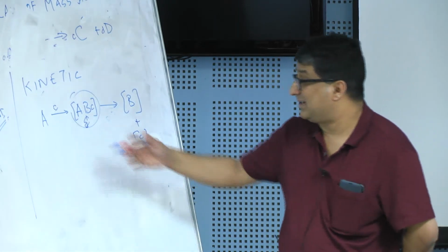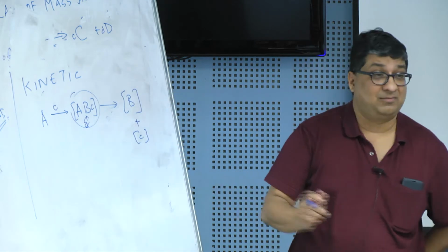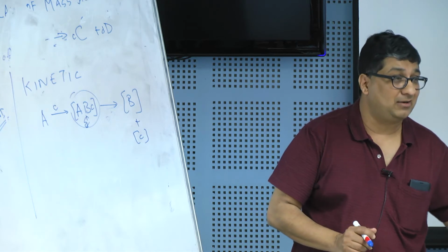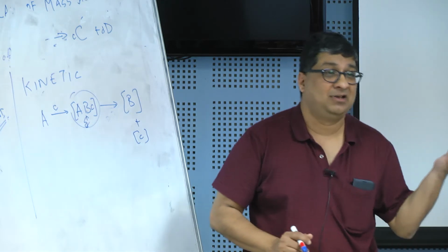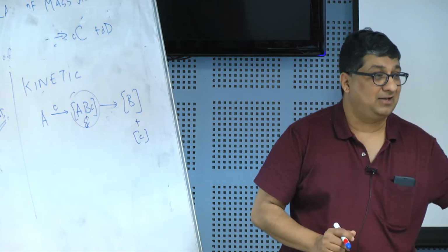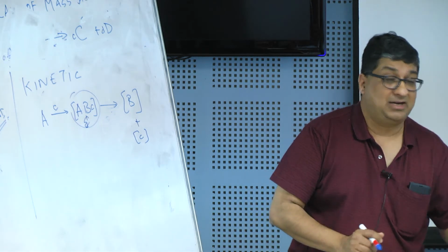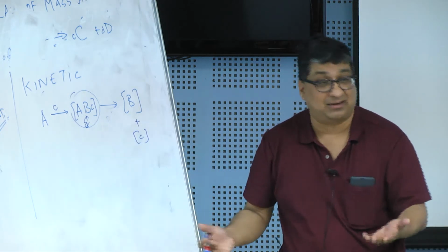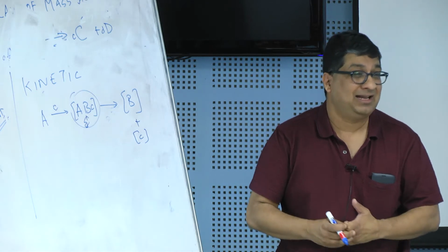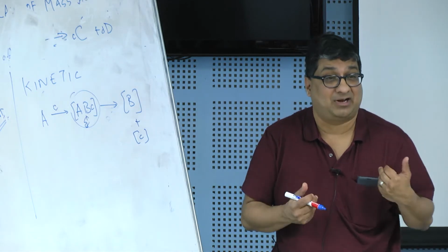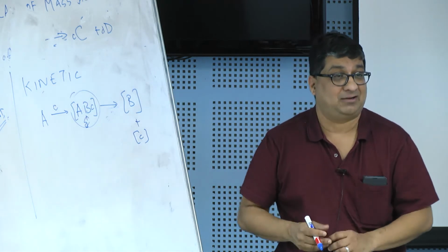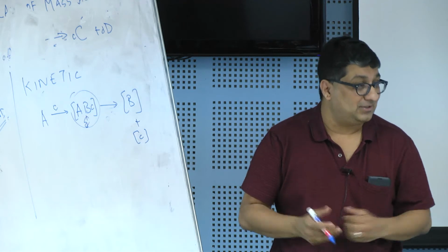So these types of reactions tend to be controlled by how much catalyst is there. Those types of reactions are all autocatalytic reactions. They are called autocatalytic because the more catalyst I have, the faster the reaction. The less catalyst I have, the slower the reaction. So the substrate in Monod kinetics acts like a catalyst, because it's what facilitates that reaction. It's not truly a catalyst because we don't recover it back. It becomes carbon dioxide at some point. So technically, we shouldn't call it a catalyst, but it serves the same purpose.